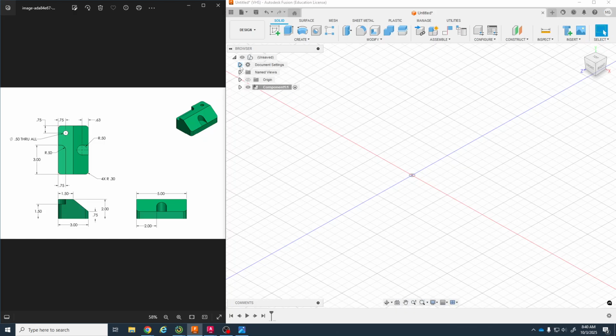So just click this little arrow and make sure your units are in millimeters. If you wanted to change it, you could just click this little button. This will pop up and you can change your units. In my other class, I think I did inches, but we'll go with millimeters. The only thing is, we're going to get a different mass and our dimensions may be different at the end and it may be annoying, but since Landon started there, that's what we'll do, so he doesn't have to redo it.